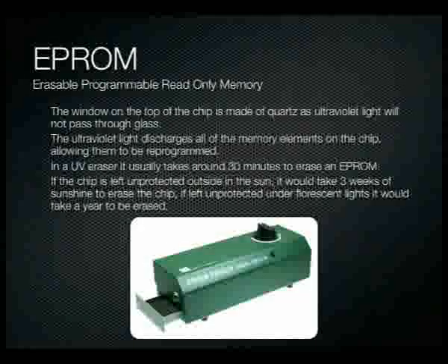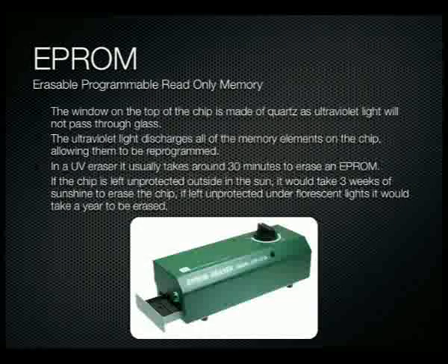So the window on the top of the chip is made of quartz, as I said, and this is because ultraviolet light will not pass through glass, so we make it quartz, and therefore ultraviolet light will pass through that quartz and then affect the actual memory elements and get them to discharge.